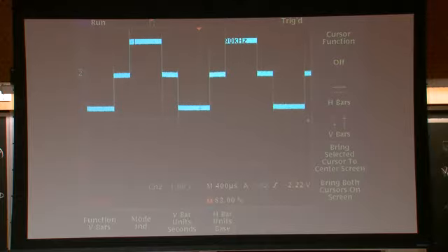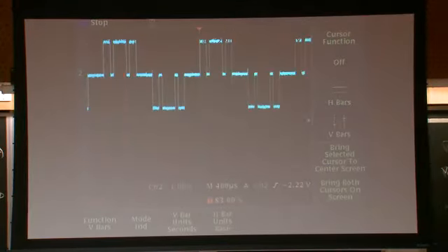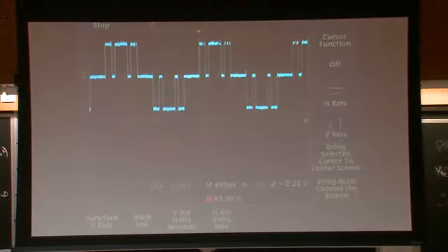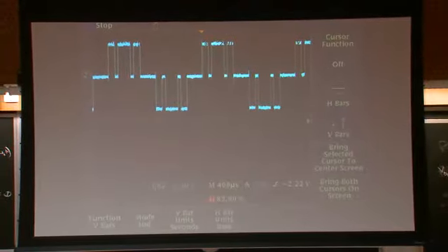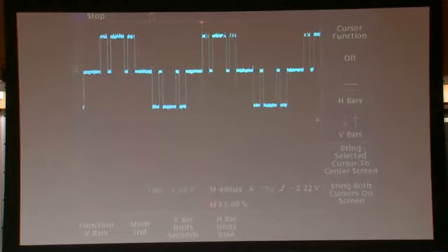Now, let's do another thing. Like we saw in class, if we introduce pulses or notches on both sides of the waveform, it's still half-wave symmetric. So we're still doing the same thing, but interestingly, if we move to the second highest spike, it's at about 4.2 kilohertz, which is the seventh harmonic. So we eliminated the third and fifth harmonics.